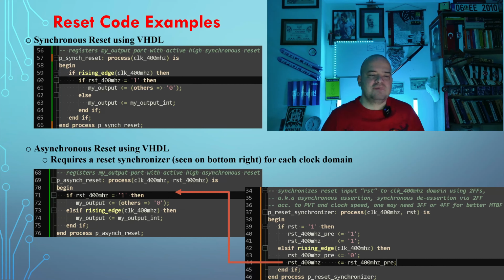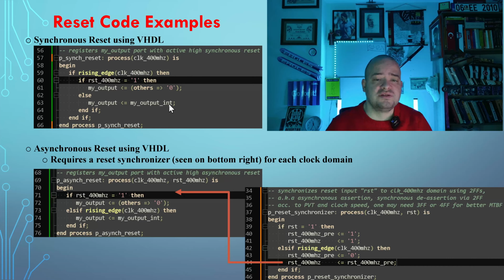So it depends on many things, but one of the major drawbacks, which I will cover at the end: if you don't have built-in synchronous reset inputs, then this type of approach consumes one of the lookup table inputs. Let's say you have a 6-input LUT technology, one of the newest ones. Then if you code like this, that lookup table will behave like a 5-input LUT, which is an older technology.